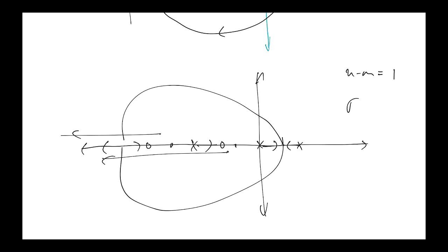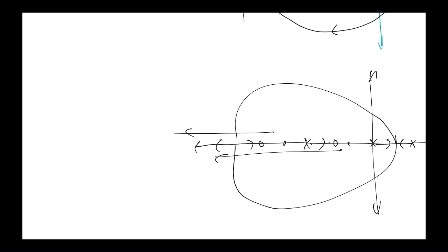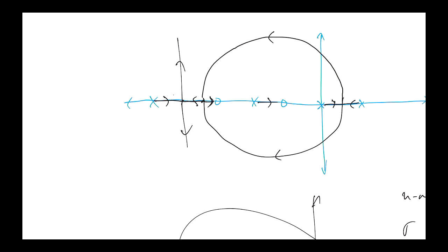Okay? So, if I put a very high frequency, very fast pole down here, then it's going to look something like this. And why might I put a really fast pole in here? Well, to make sure that my controller is proper. If I don't put this guy in, then my controller is not proper. It's got 2 zeros and 1 pole. And we've seen that you can make controllers proper without affecting what's going on much by just adding a very fast pole. And so if I'm adding a very fast pole, it's probably still going to do this, and then this and this guy are going to meet together and go off like this, as I showed originally.